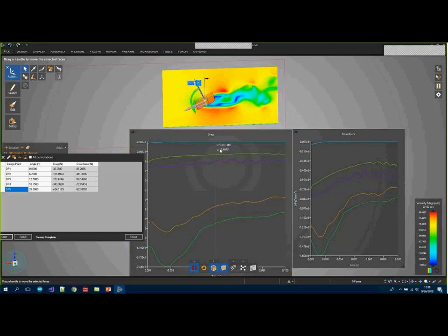So here are our results. We can see the plots. Everything looks good. Right? We can find here that probably the best option is 12.5 degrees or somewhere in between there. Right? From 6 1/4, the drag increased by maybe a little bit less than a factor of 3, but the downforce increased roughly a factor of 4 plus, nearly 5.